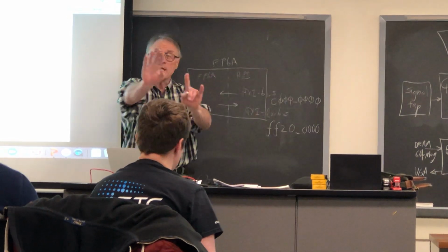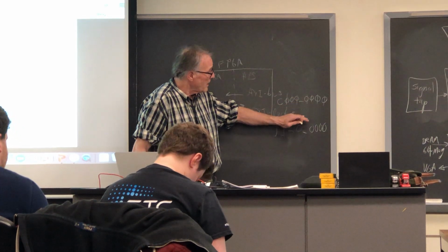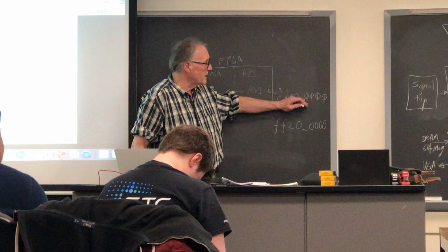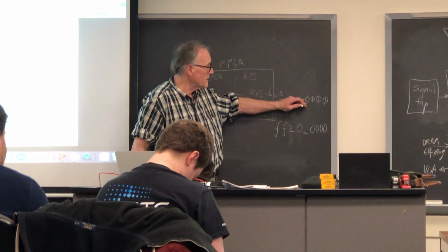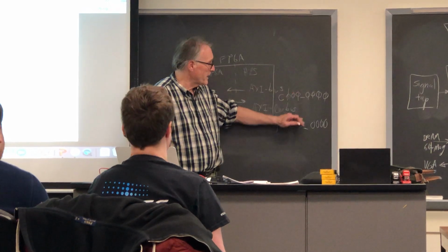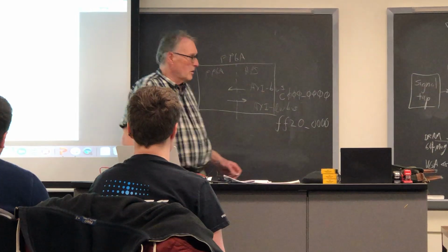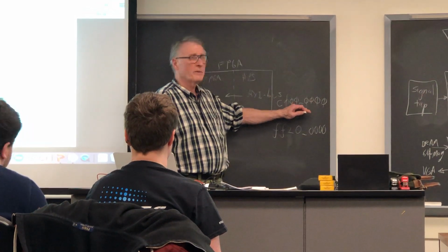So from the HPS side, every bus address that you mess with on the FPGA is going to be in a range starting at hex C000 or hex FF20. The size, the span of this boundary region is about a gigabyte.